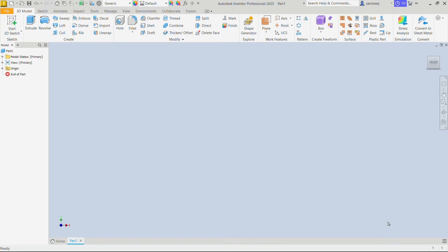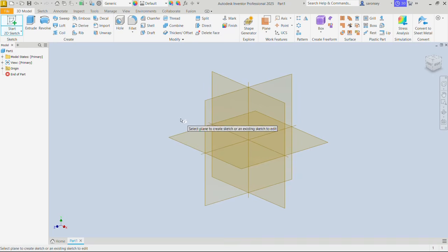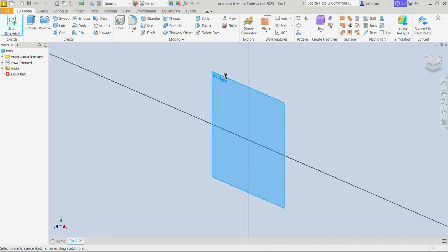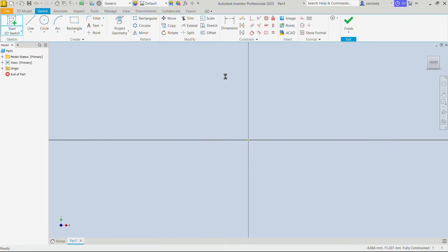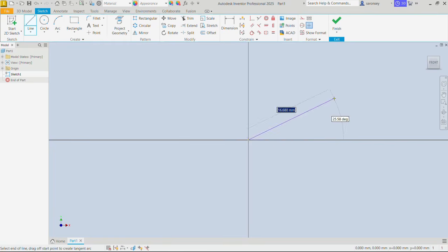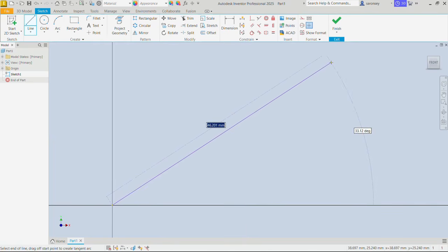This is the path we would use even to build our belt, and also we will put some points on there so we can place the bucket rightly on those points. To draw the path, let's pick the 2D sketch command. We want to create this sketch on the XZ plane. Now let's pick the line command. Let's draw a line from this point here. This much is fine. You can drop this here. You can right click OK.